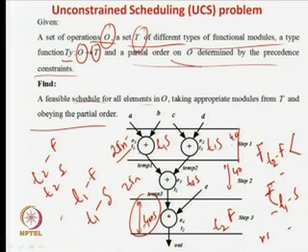So, what I will do is that a typical intelligent designer will put in a 40 nanosecond multiplier, which is the fastest available. And here he will not put a very fast adder, he will put a very slow adder, because he is getting the answer in 25 nanoseconds, which is much less than 40 nanoseconds. So, anything below 40 nanoseconds is okay.